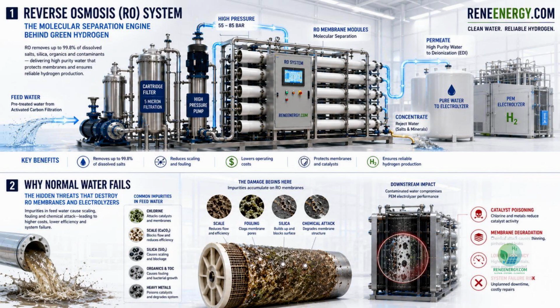Image 1 shows the complete RO system. Feed water enters from the left side after earlier pretreatment, such as filtration and activated carbon. Even at this point, the water may still contain dissolved salts, silica, organics, bacteria, and minerals. The high-pressure pump drives that water into the RO membrane modules.